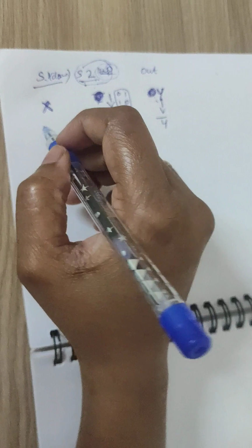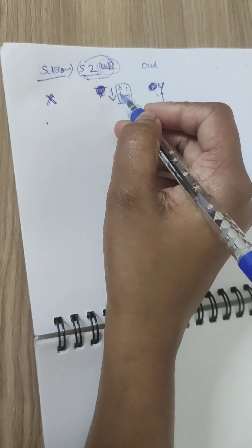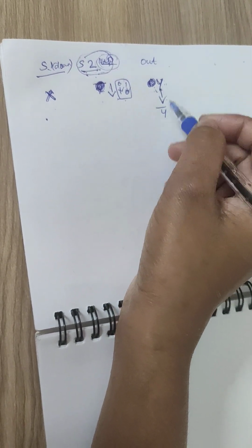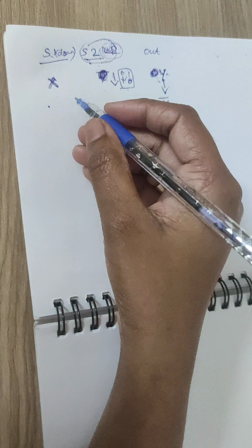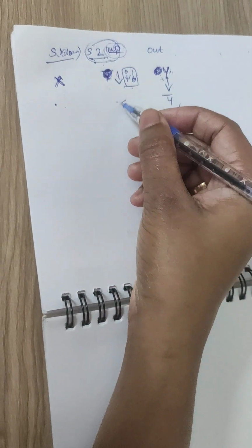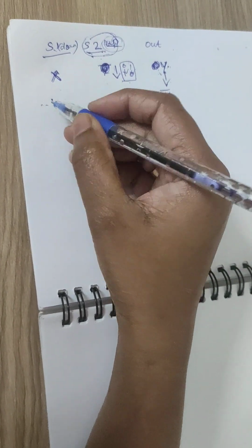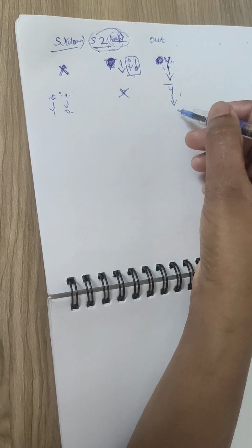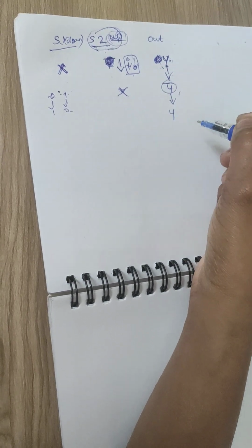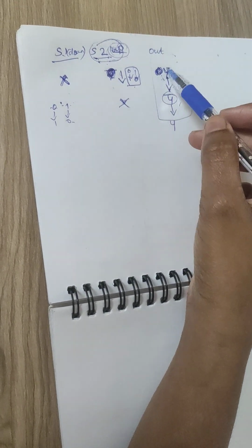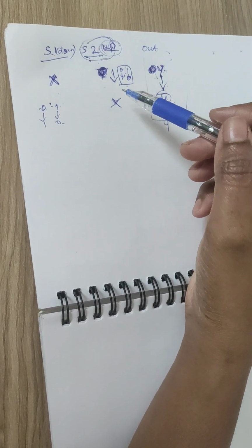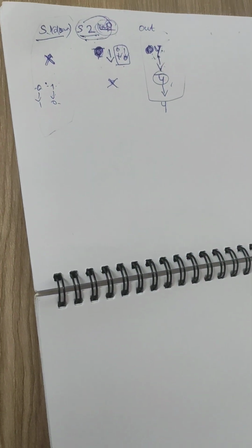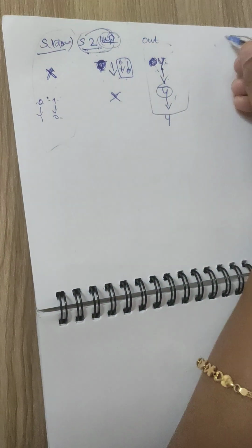Likewise, if the other input is the don't care and I am here, I change my input from 0 to 1 or 1 to 0, and again the output, if it was y bar previously, needs to become y. Toggling needs to happen at the output whenever one of the inputs is stable and the other input is changing. That is our expectation.